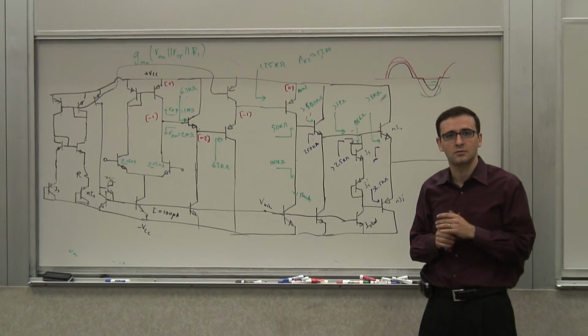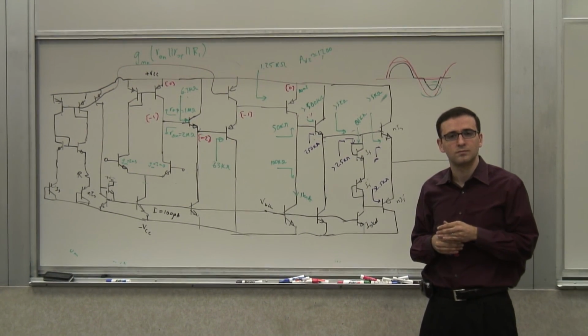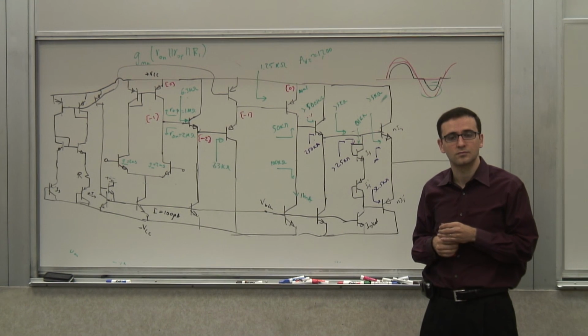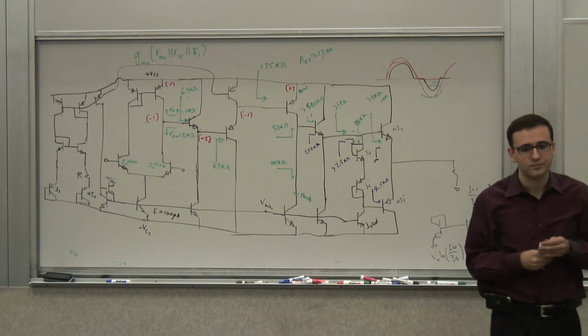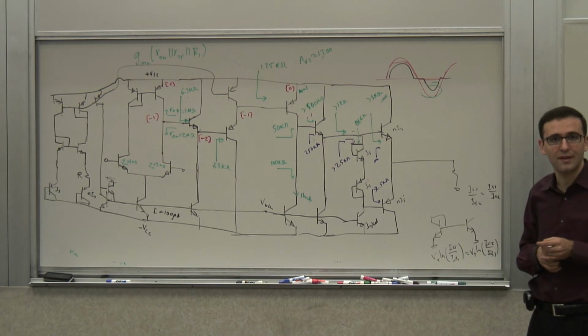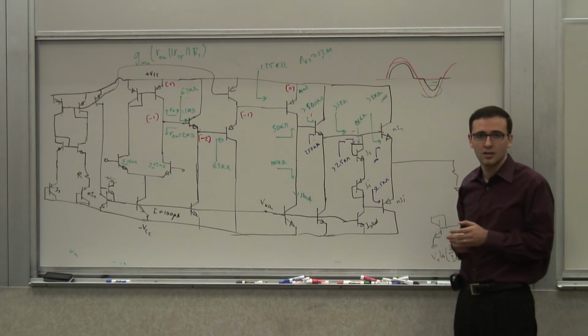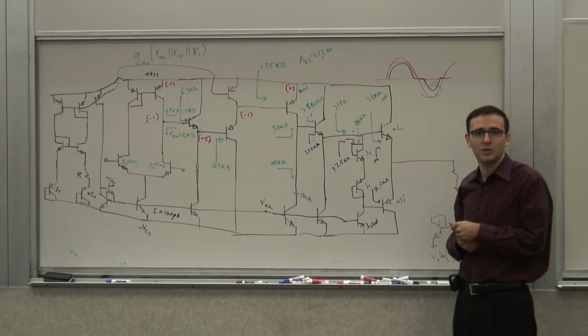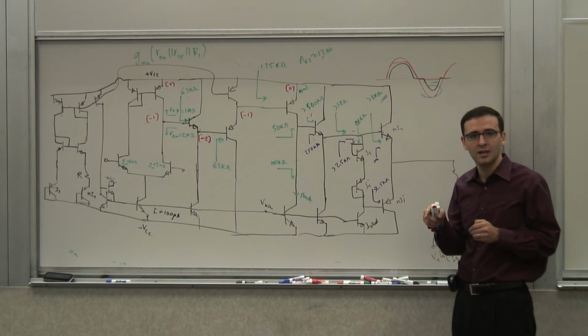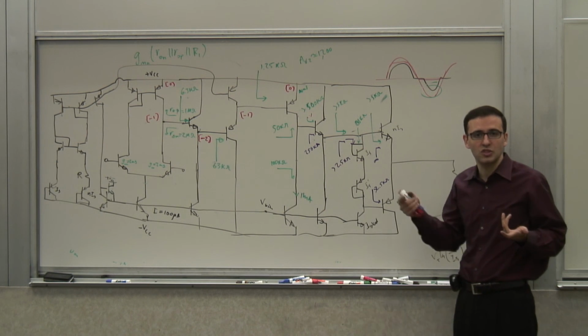Yes. So does the input resistance of the output stage, it being different for the different modes of operation, affect the gain by a lot? Yes, your gain becomes operation point dependent, right? But your gain is almost always operation point dependent. Even if you look at a common emitter, it's GM RL, but GM depends on the current.